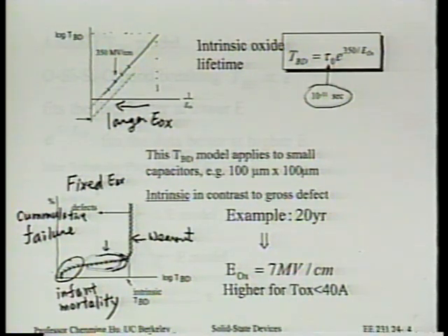All right, so. But we do know that thinner oxide can tolerate even higher field, such that today the highest field that's used in production is actually pushing to 10 megavolt per centimeter. For example, let's say a 1.8 volt process, 0.18 micron technology. Do you know what's the oxide thickness? Do you know what is the oxide thickness? Roughly? 0.18 micron technology.